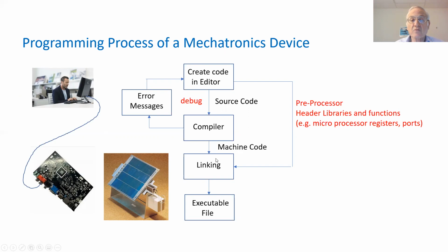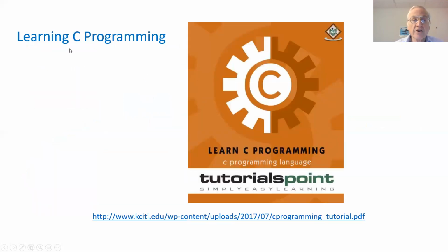And then it will be linked with the preprocessor header library, and could also be linked with microprocessor registers and ports. And this will then generate the executable file. The executable file is downloaded to the chip, and then it can be used on a PC board to drive a device.